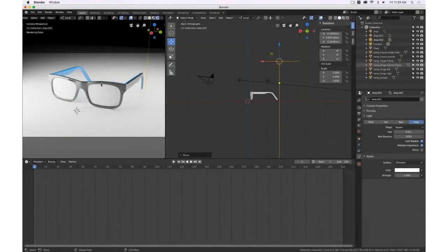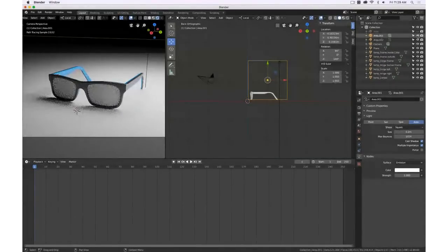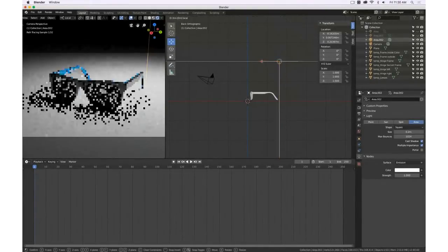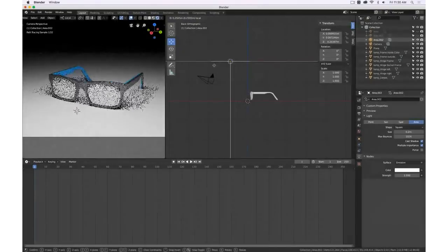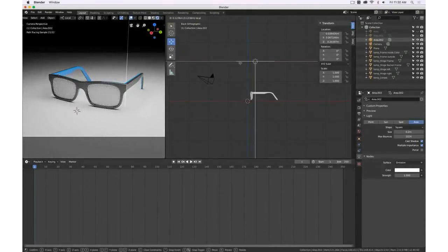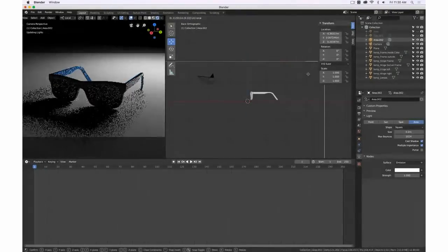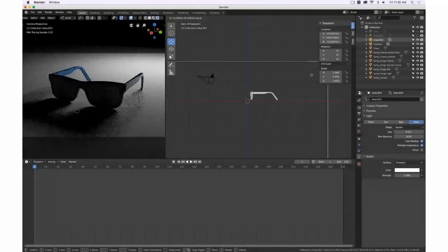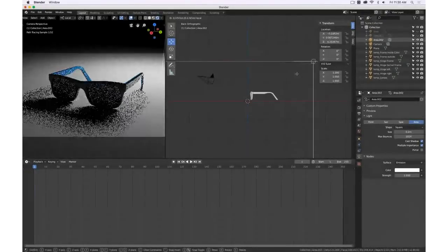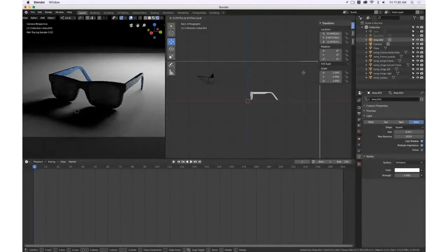When you work with lights, here's another interesting trick. When you select these lights, you see them here being highlighted. So I can turn off the eyes here. That means they're currently not being used for rendering. Now I only have 1 light, and when I move this around, I can better study how this creates, for example, highlights.